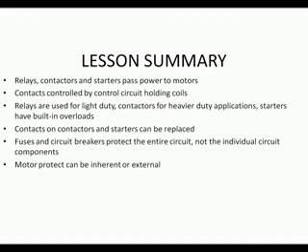Once a motor trips on an overload protection, it should not be restarted immediately. The cause for the overload condition must first be located and repaired, and the motor should be given ample time to cool. Manual control devices are manually reset. Some controls reset automatically after a predetermined time delay. The time delay feature prevents short cycling, or the constant on and off of a motor failing. Bottom line is, the motor will not fail on its own. There's some cause that you actually need to find before you reset a motor.